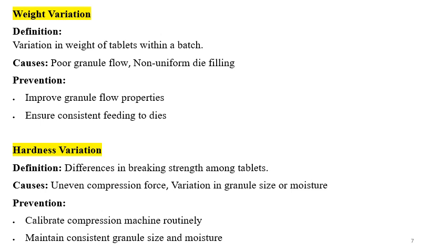Then hardness variation. So differences in the breaking strength among the tablets. Tablets are required to be sufficiently hard to meet the friability requirements and to meet the strength requirements for the proper handling. If the tablet is required to be coated, that time hardness is required. Hardness is required to maintain the handling, transport, and meet the friability.